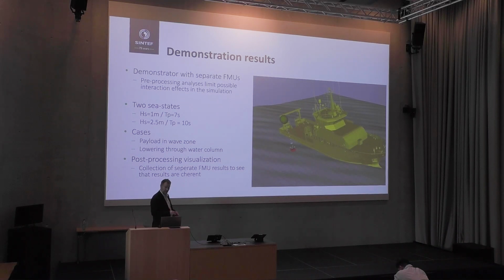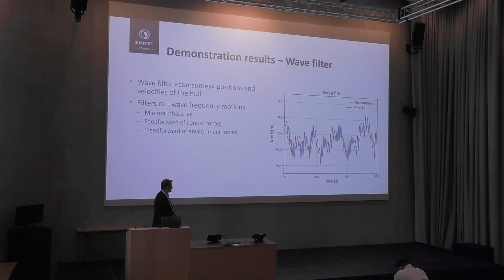Another work package of this SECO project is coordinate transformations, and we worked a lot with that in the same time. So we have one type of FMU in the control system that interacts with the environment by the motions of the vessel. Its job is to remove wave frequency motions and make something that's controllable for the system.